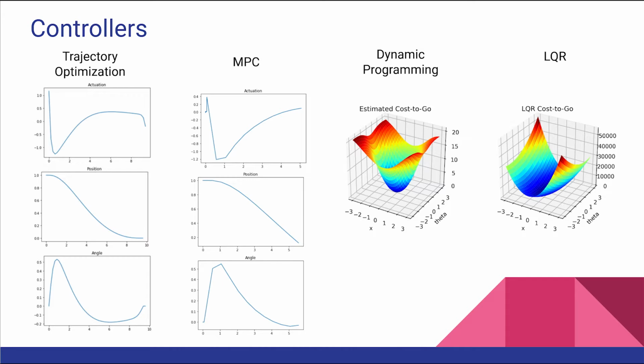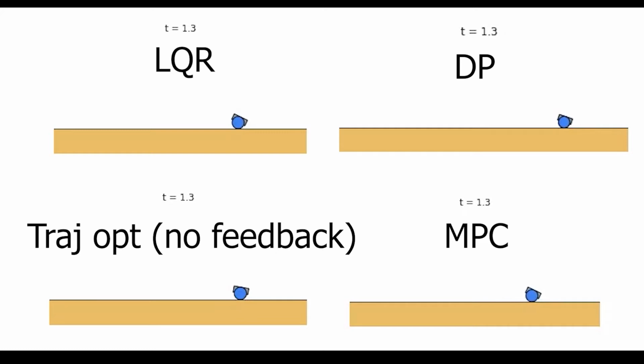First, Jorge created a neural network that, once trained, could approximate the cost-to-go function and incorporated this in a dynamic programming approach. Second, I used Drake's mathematical program with various sets of constraints to develop a trajectory optimizer. And third, Fischer used this trajectory optimization code as a base for model predictive control to iteratively choose actuation values at every time step. We also used an implementation of LQR from the textbook as a baseline.